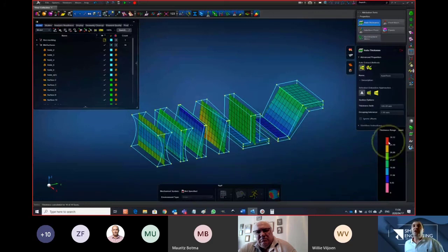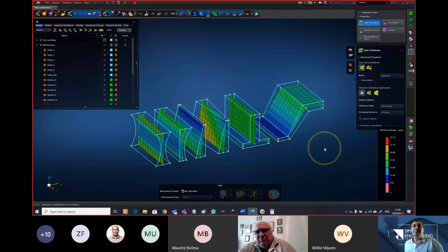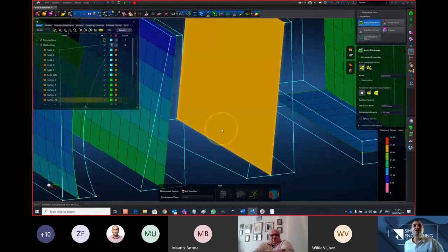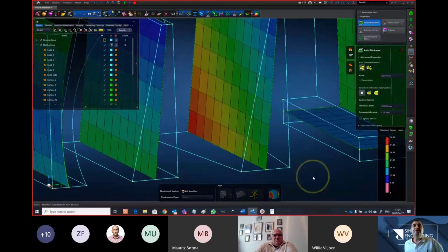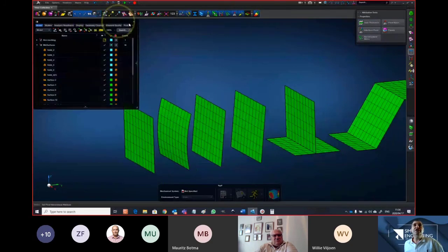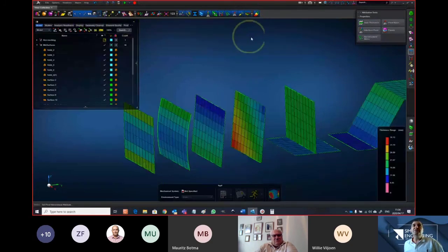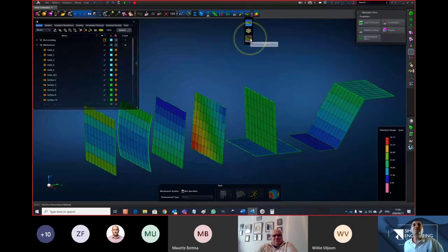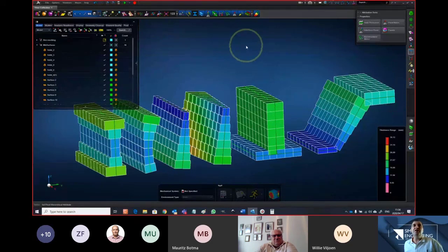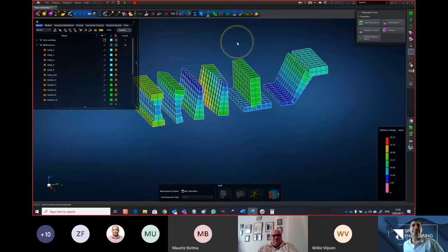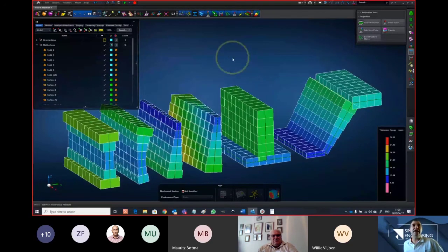So over here, it shows us the values. And as you can see, I've used large elements. So obviously, each element will have its own thickness now. And I can also render it. If I just hide my solids, I can render it in various ways, either through the fringe method or the physical solid method. So this now shows me exactly what is happening mathematically with my thickness and elements.